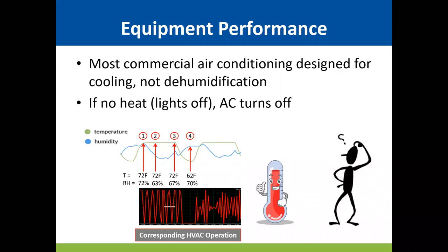Well, there's no heat gain to the room. So your thermostat's like, hey, I'm cool, right? Literally, I'm cool. I don't need to do any work. And your air conditioner turns off, like, I don't need to work because the temperature is fine. And you're like, oh no, what just happened? Why is my humidity spiking at night? Because your air conditioner turned off, right?